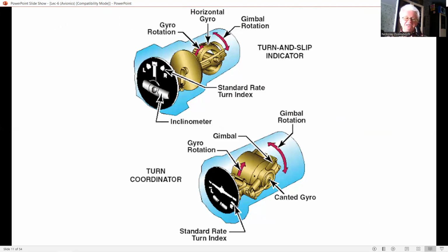And this has the advantage that the key motion feedback sensors, namely the pitch rate gyros, are very rugged and reliable devices. Solid state rate gyros are very reliable sensors with an MTBF in the region of 50,000 up to 100,000 hours. So fit and forget device. And this is very nice.